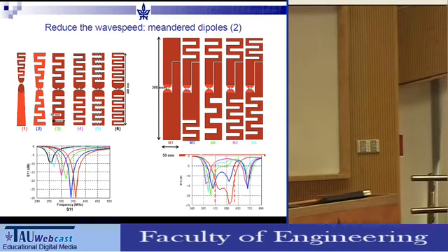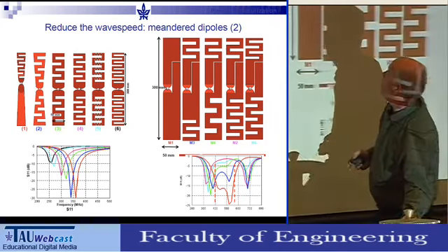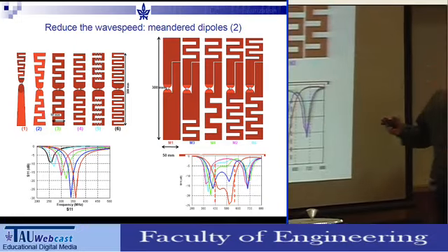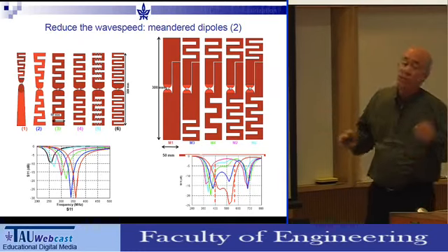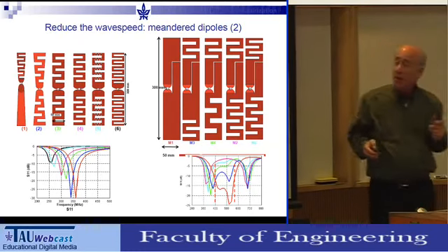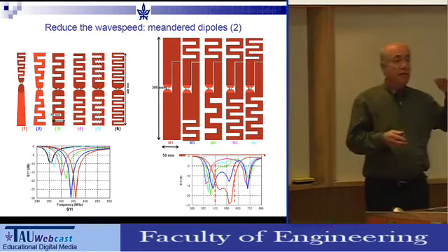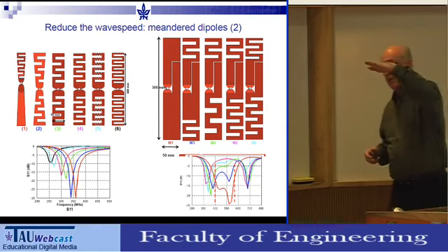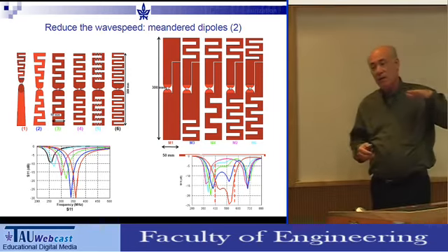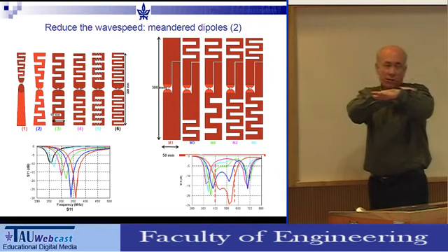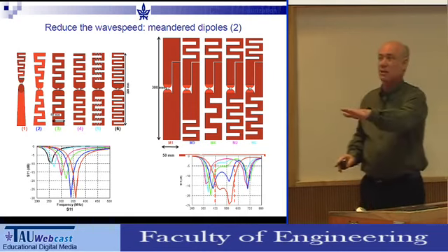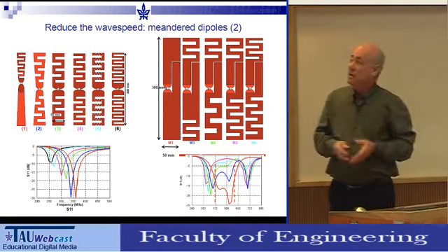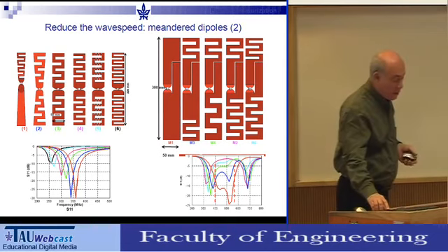that if you do that, you have to be very careful, because you cannot really expect the current to keep flowing along the meanders the same way it would flow along a long straight line. What you need to make sure is that if you're looking at the current in one meander, then you have to go around, and the current in the next meander should go in the same direction. Okay? And if you have another one, still in the same direction. So it is an art. People try to get a hold of it.